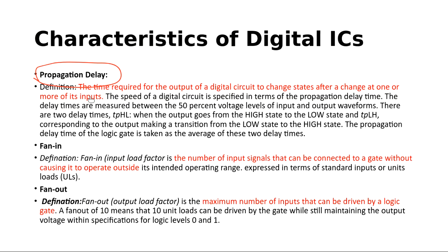Logic gates behave according to input logic, and depending on the input logic, they give you one output logic. So it's only the time delay between input and output, how fast a logic gate is able to give you the output. Your processor speed, your mathematical function performance, the speed of your calculators, computers and mobile phones will depend on this propagation delay.